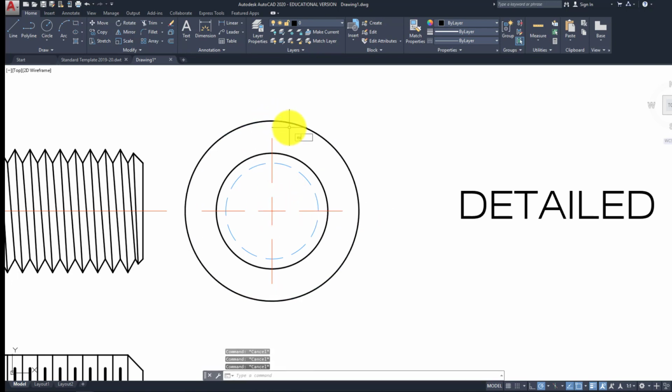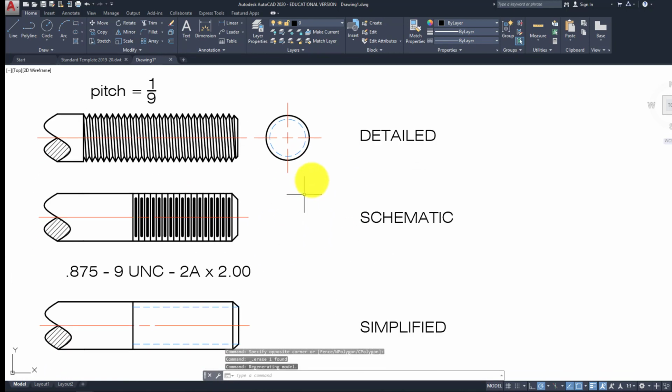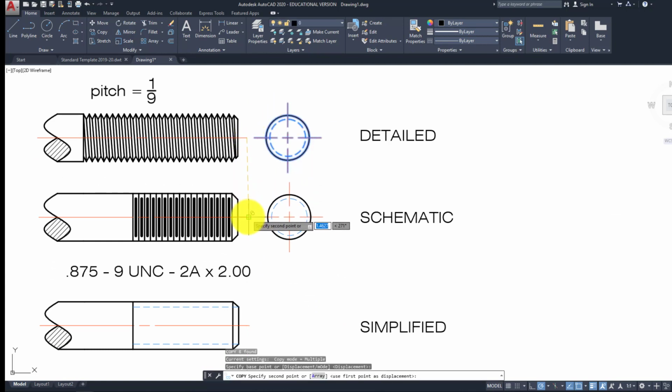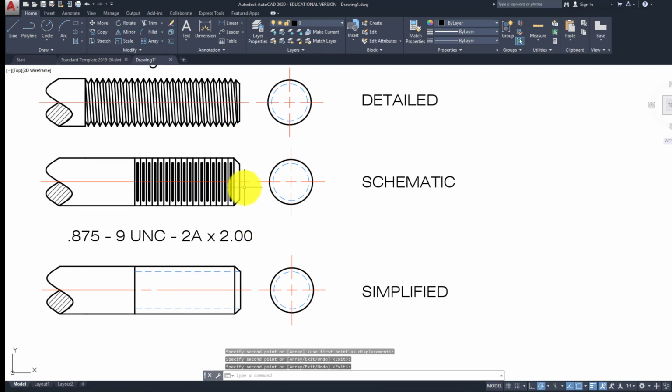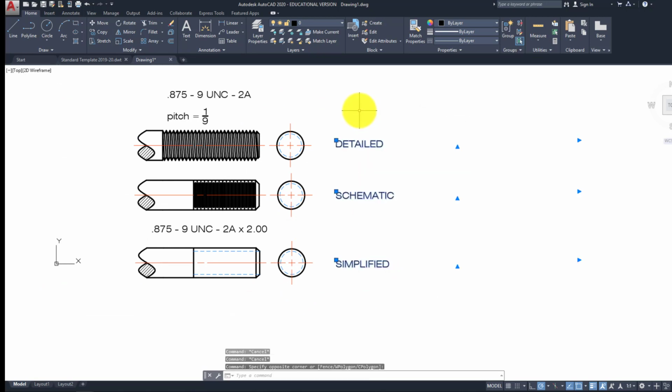I'm going to use the extend tool, EX, right click, and just make these a little bit longer because you never want your center mark and your extensions to be remotely the same. And I think those were. There we go. And guess what? It's the same for every single one. You can see how I shifted those ones over. It doesn't matter. Alright, perfect.